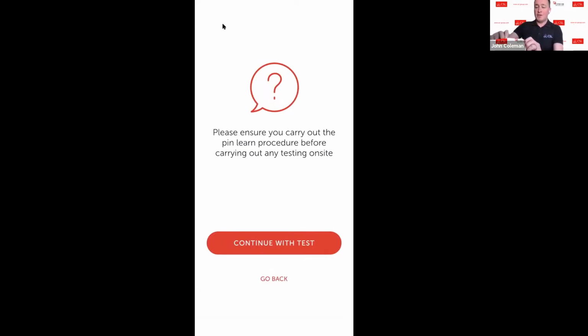So if I press and hold the C button for approximately 5 seconds, the amber light will give a brief flicker, and then I've done a pin learn. One of the things that we get lots and lots of phone calls for within the tech support team is about doing pin learns, etc.